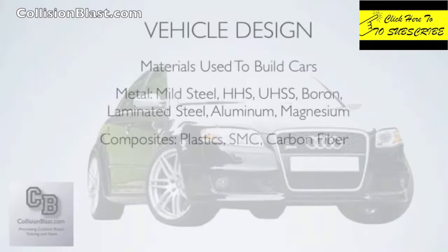And also, the government is still wanting better fuel mileage, so I think you're going to see a lot more plastics. I mean, there's already a lot of plastics in SMC, which is sheet molded compound. Basically, that is a fiberglass, fiber reinforced plastic. But you're going to see a lot more of those because they are a lot more lightweight than some of the metals. And carbon fiber, there's some of that out there already, but I think we're going to see a lot more of that because it's super strong and really lightweight.